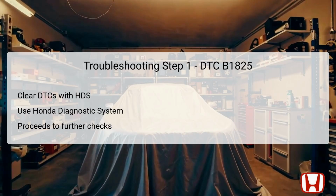The first troubleshooting step for DTC B1825 is to clear the Diagnostic Trouble Codes, DTCs, using the Honda Diagnostic System, HDS. This process involves connecting the HDS to the vehicle's onboard diagnostics and selecting the option to clear any stored codes, including B1825, from the system's memory. When DTCs are cleared, it allows technicians to reset the system and can sometimes resolve minor transient issues. However, it's essential to ensure that the clearing process is appropriately conducted to maintain data integrity for future diagnostics.